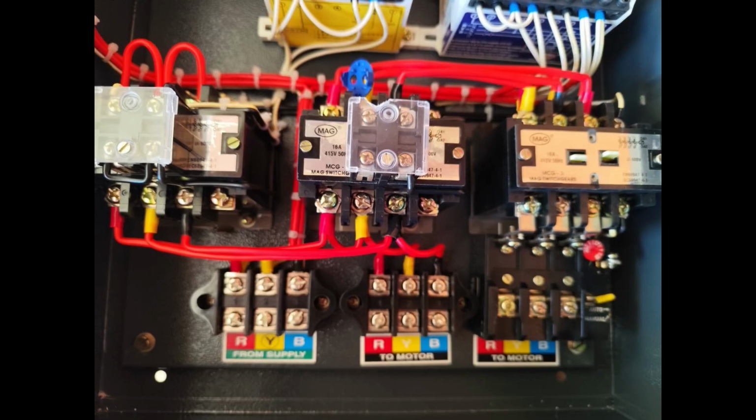The first contactor is main and star, the second is delta 1, the third is delta 2. The first contactor achieves the star and main operations. The second contactor achieves the delta contactor and parallel connection of supply. The second delta contactor achieves the delta configuration. Important points of operation: supply is on, connected 3 phase.